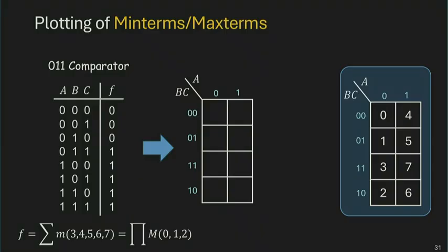All right. So how do I put a function in a Karnaugh map? I'm going to do some plotting. By converting a minterm expansion, and that's a maxterm expansion for the same function, I just have to look for the cells corresponding to each index, and then fill it out with zeros and ones.